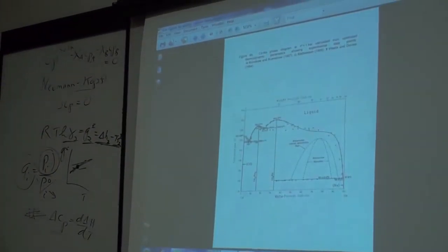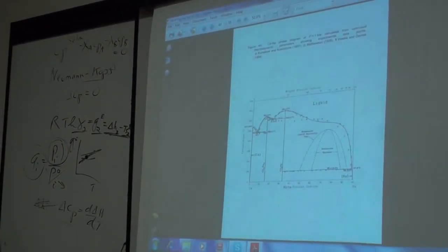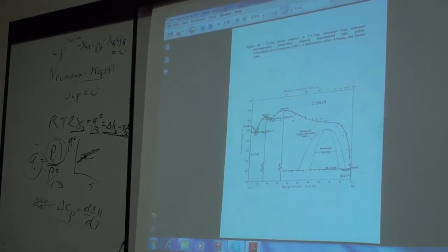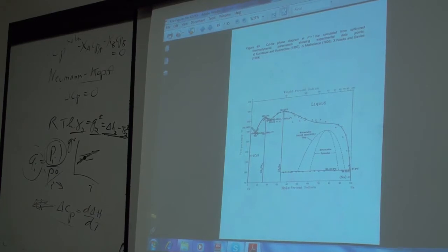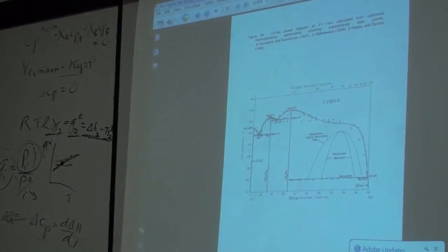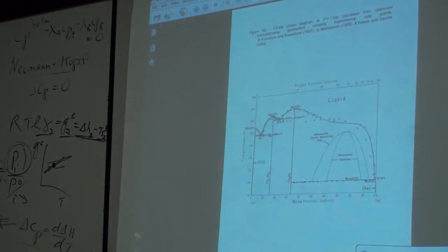Remember, what have we measured here now? This liquidus is here for cadmium. Only over this range do we have the activity of cadmium measured from the liquidus, and it's almost going to be Raoult's law over such a narrow range. If we knew the heat of fusion of this compound, then this is the liquidus for this compound. If we knew the heat of fusion of this compound, then we could, along this line and this line, obtain the activity of that compound in the liquid phase.